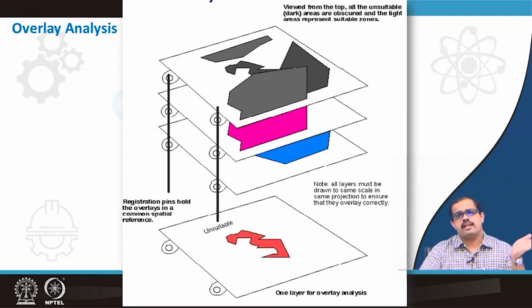So, you will adopt maybe any fuzzy analysis, which is advanced spatial analysis, or it may be your AHP. You try to say that this is the weightage of this particular layer, or this is the importance of this particular layer in this particular analysis. So, with that you will also find out where actually the drainage network is blocked and where the flooding has happened. So, if you can understand that the flooding is happening because of the blockage of drainage network, then it is a highly sensitive area. So, that is how you can come up with a flood vulnerability map, which is actually addressing the urban floods in that particular region.